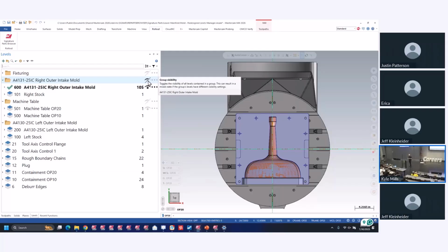I absolutely love that workflow. I get to see what's on. I use that in tandem with view sheets, and I can see exactly what I'm working with. With the filter, we have quite a few options. We still do level number, just like before. We can do name. We can do entity count. So if you have something that has a ton of stuff, maybe like a wireframe level with all your wireframe in there, you could get that to the top.